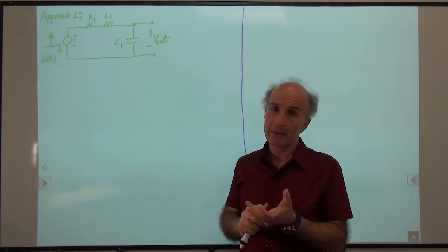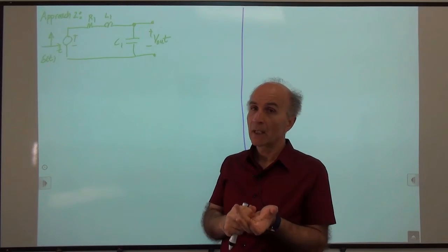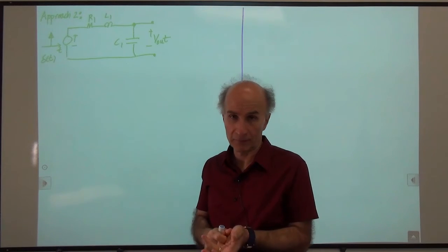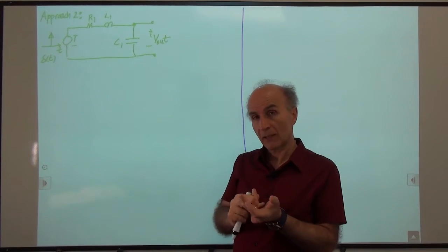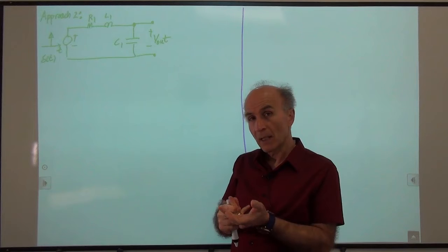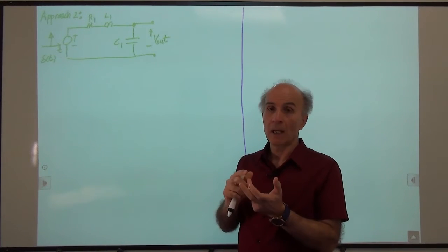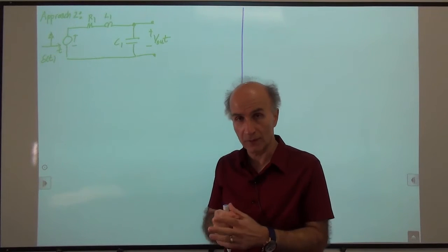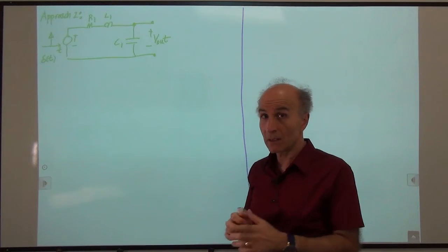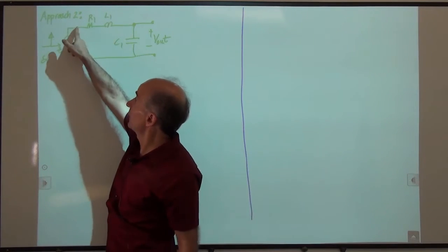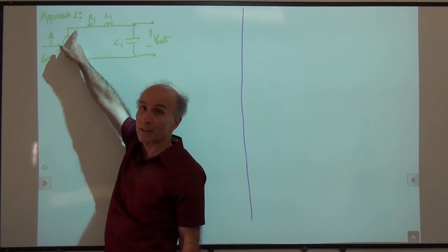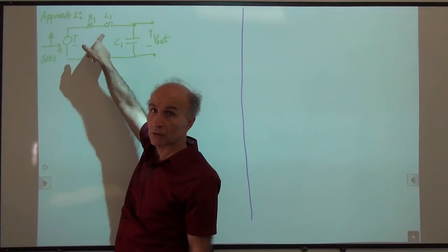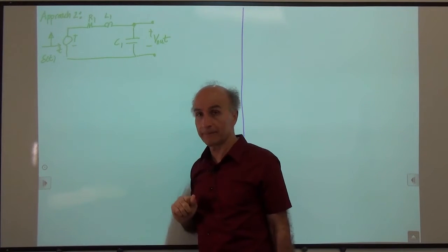We said a capacitor cannot jump its voltage if the current available is not infinity. An inductor cannot jump its current if the voltage available to the inductor is not infinity. But here, we have an infinite voltage briefly, and we have to ask ourselves exactly what can change in this inductor or in this capacitor.